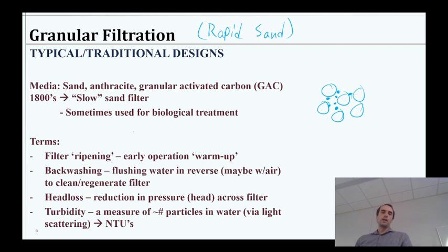So that's pretty obvious. Sometimes we'll take some time to do an air purge. So we push air up through these granular media. That really helps to rattle all the particles off the granules. And so we'll often do an air purge and then send water up through. See a video of that in a few minutes. So that's backwashing. Essentially, that's the way we continually reuse these filters without worrying about the particles eventually making their way out, right? Because that's kind of the thing we want to avoid most.